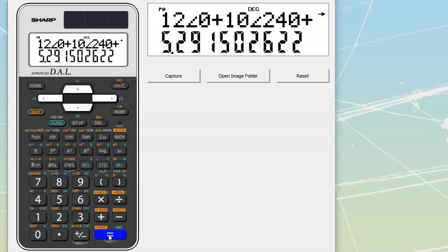And we're going to hit equals, and it tells us that we have got a magnitude of 5.29 amps, so that's our total amount of current, and that the current is coming back along an angle of negative 40.9. Now the negative 40.9 doesn't mean anything. We don't need to graph it, we don't need to draw it or anything like that. We could draw it onto this other vector that we have, and maybe we will here in a second. But it is telling us that it's just out of phase with everything else.